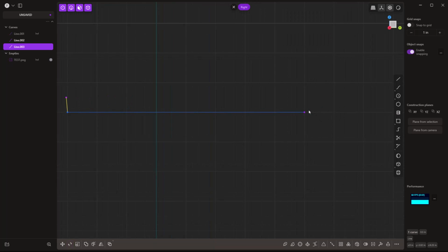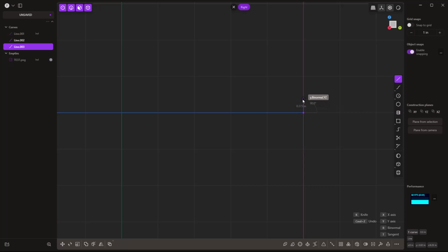When we come over here to the back, I again want a 5 degree or a 0.5 line. So I'm going to hit tab, 0.5, but before I hit enter, I'm going to tab again, and I'm going to put 95 degrees here. Now, as soon as we enter that value, I can actually jump back and forth between 5 degrees in the positive direction and 5 degrees in the negative direction. Plasticity doesn't really care. So that can be a kind of handy thing. And then once we're happy, just left click to accept that, and you can keep sketching another line, or we can right click to confirm and be done with it.